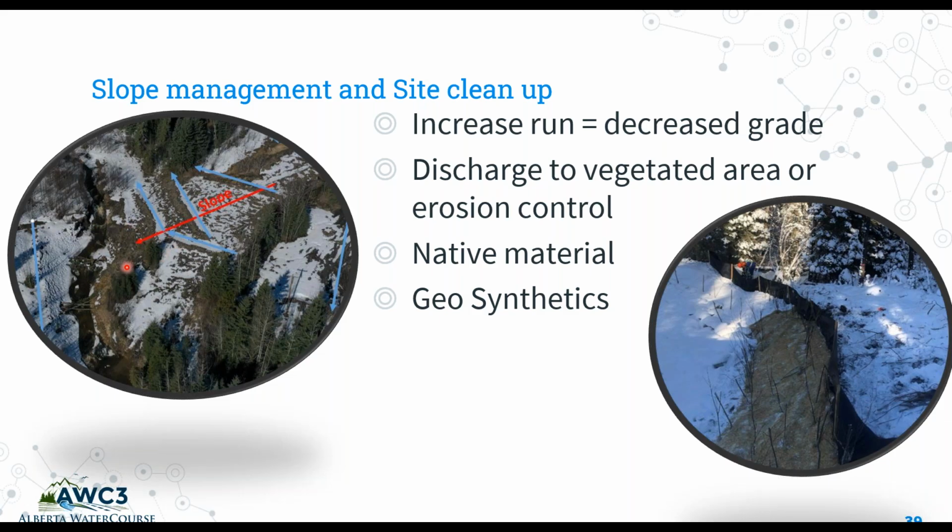Not only have we decided to make sure our slopes are rough and lumpy, but we've also installed diversion bars or berms that are increasing the run of the water discharged into a well-vegetated area, decreasing grade and speed, and controlling water from entering disturbed areas. Erosion control can also be done with geosynthetics, such as silt fence, coconut cloth. There's a variety of options. Just ensure you have a proper slope management and site cleanup plan.